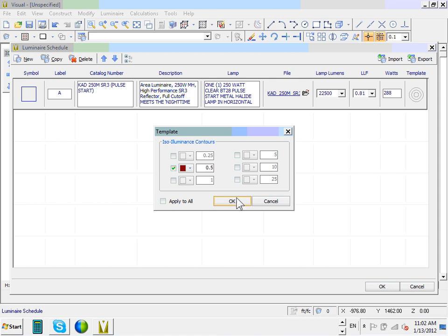That's my cutoff. How do you know from looking at that what is what? It just gives you 3 blocks with check marks. Yeah, it is 0.25, 0.25, 0.1, 5, 10, and 25. How do you know what that 0.5 is? 0.5 is a foot candle. I'm telling you, we picked the 0.5 because it says 0.5 minimum. But what visual clue tells you what you just selected? ISO illumination contours. You have to know that.